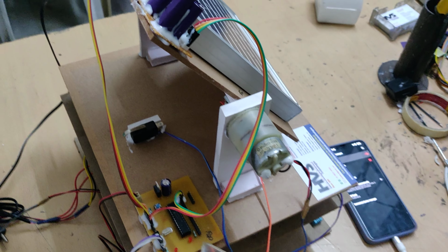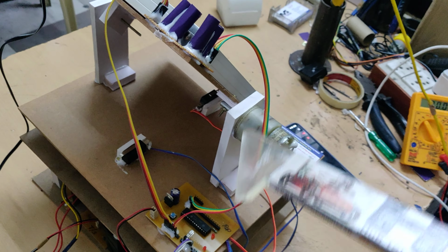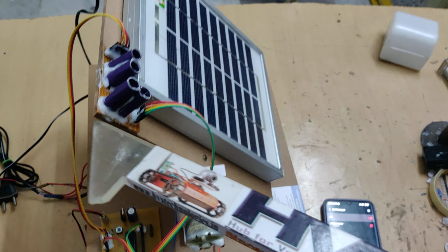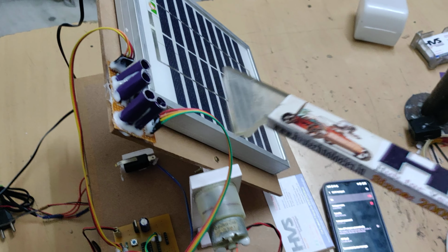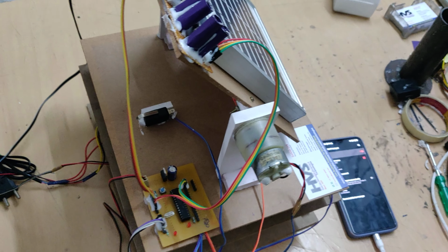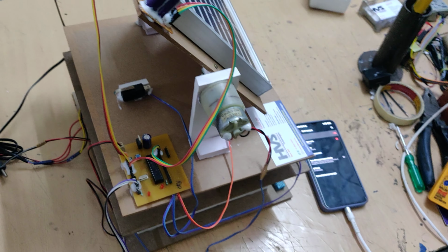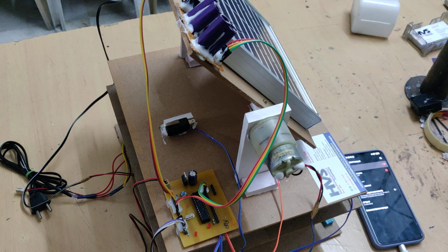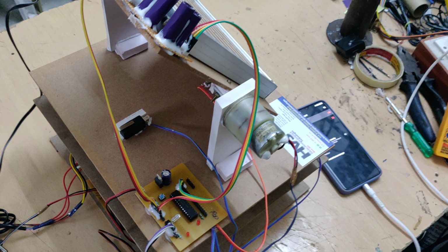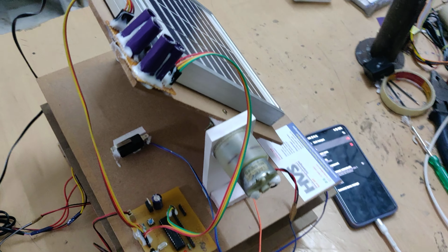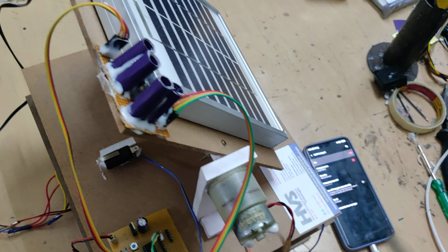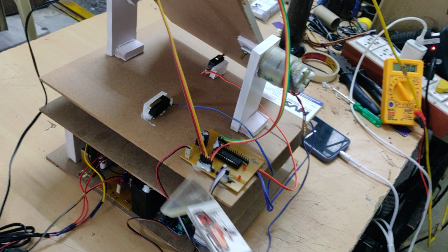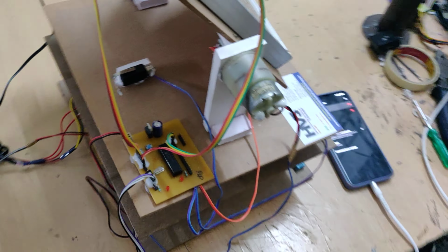With the help of this, we are going to do the solar tracking system by getting input from these 4 LDRs. 2 LDRs for east and west deviation and another 2 LDRs for north deviation. So during winter time, the sun will deviate towards the south direction, so in order to detect that position when it deviates to the south. Right. So during the winter, when the sun deviates towards the south direction, that will be identified by these 2 LDRs, and for that purpose we are making use of another extra DC motor which was attached to this total platform, so that will be controlled in Y direction.